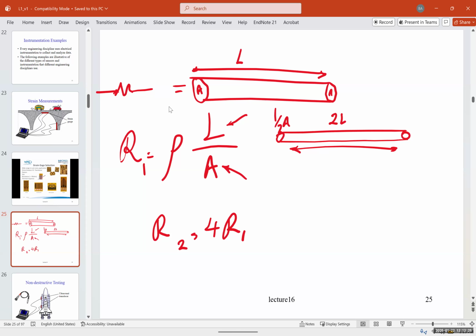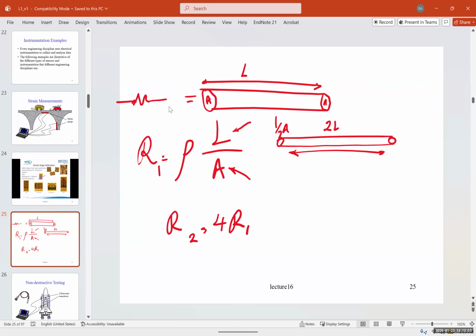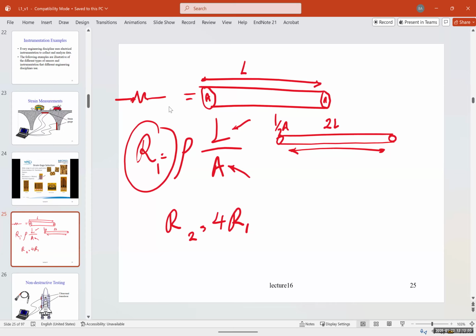And then each time a truck passes, the bridge starts to bend a little bit. The stress sensor is pushing, and the same thing on the poles as well. So when a truck passes, this strain gauge is compressing, and it's the opposite when you stretch it compared to compress it. And then you can measure how much stress is on this bridge. So using basic principles and by measuring this resistance, you can measure how much stress we have on the system.